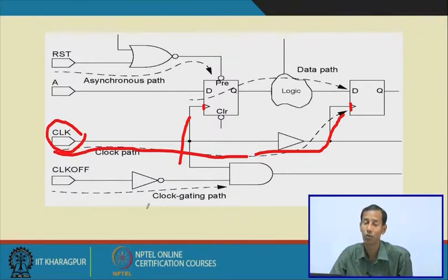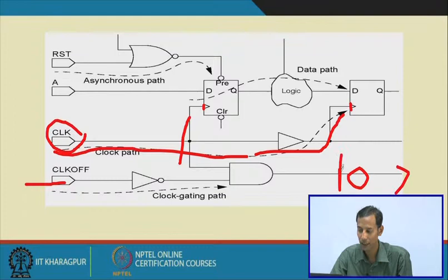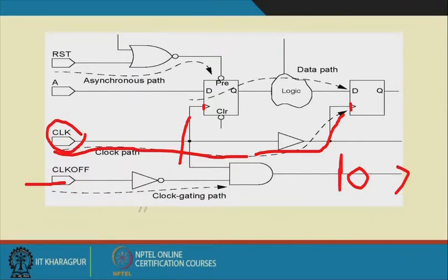Then, if I need to do clock gating, clock gating means that at some time the corresponding clock will be off, if in some condition I need to stop the clock. So, what will happen is that this is one signal which has been ANDed with the corresponding clock, and it has been applied to some other sequential element. So, this signal is basically clock gated, that means the clock is ANDed with some other signal. That is why this is known as clock gating.